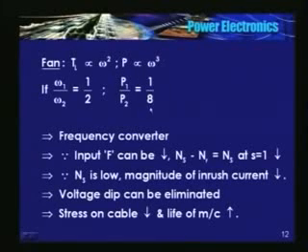See, there is a significant reduction in the power consumed if you reduce the speed of rotation. 1/8, a significant reduction. So you are trying to achieve both, save energy as well as regulate the output discharge depending upon the process requirement.